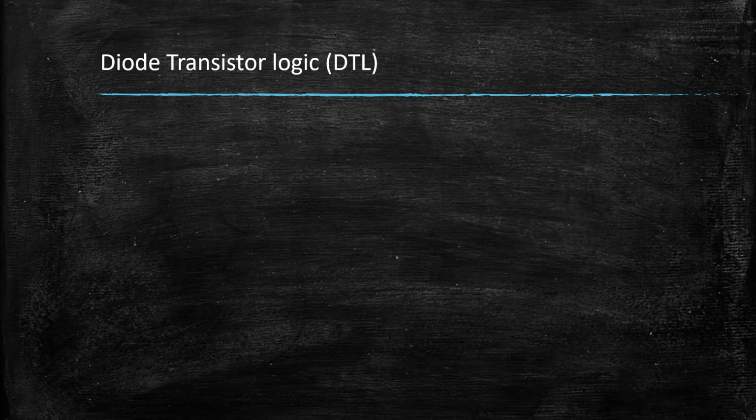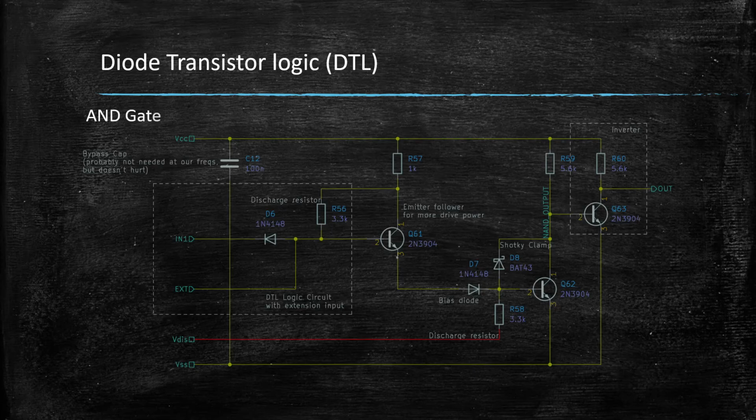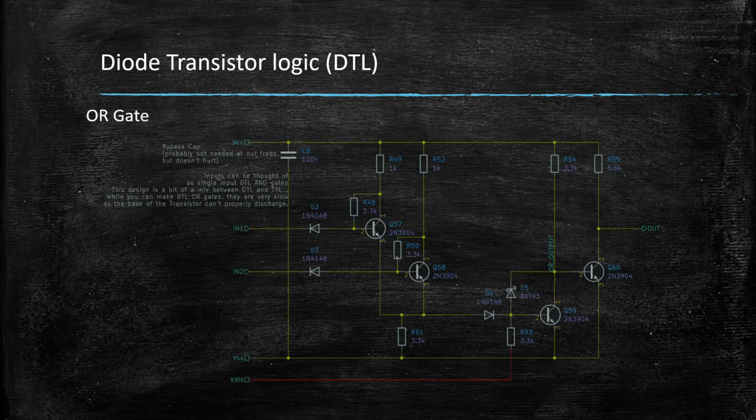Just for completeness, let's look here again at the OR gate, which is, as you see, two resistors and transistors in parallel with basically a diode input, just like our AND gate was, so that we don't have the problem with sourcing current through our load resistors. It works the same as in our Resistor-Transistor-Logic, just with the current sinking capabilities through our transistor on the input.